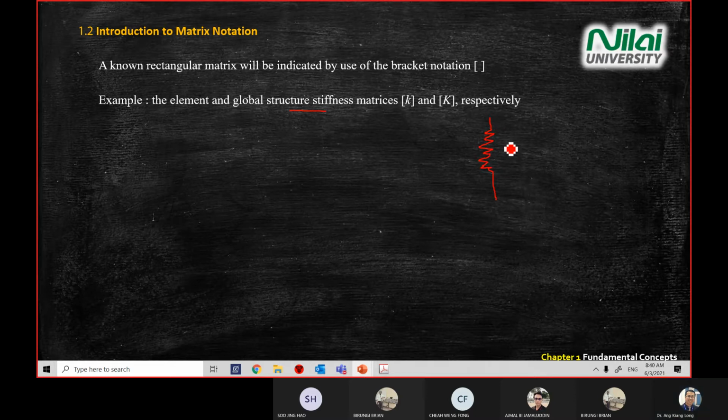The spring has a spring constant, right? This is the K for the spring. If you pull at a certain x, it will create a spring force equal to Kx. This is what you learned in the previous physics class. If you write this kind of equation in this FEM module, you need to write carefully, and if you use matrices, you transform it into this form.